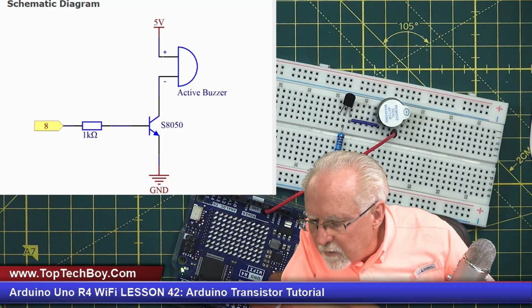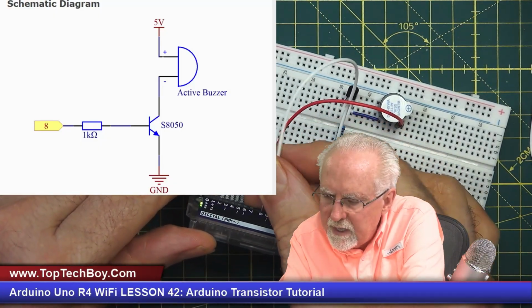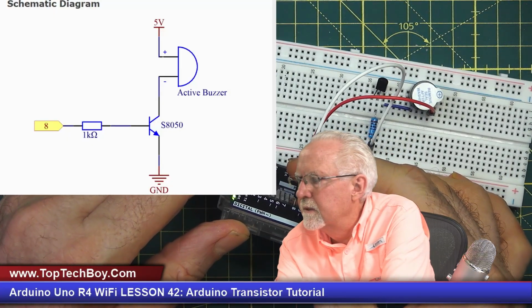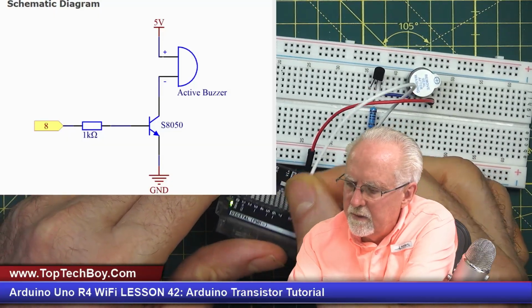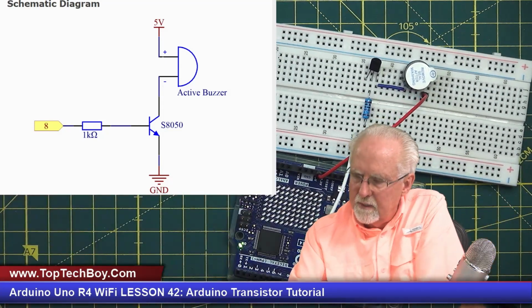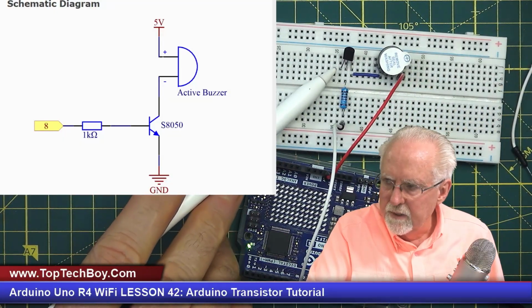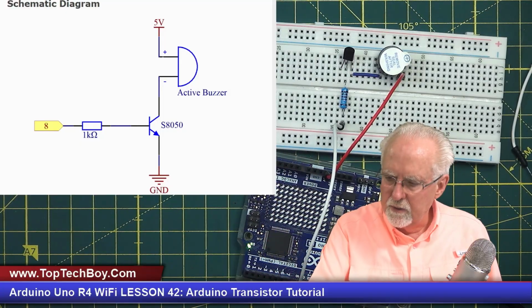So I'm going to come over and connect to GPIO pin 8. You see that? GPIO pin 8. Now, what do we do with the emitter that is on the left? The emitter in the picture just simply goes to ground.